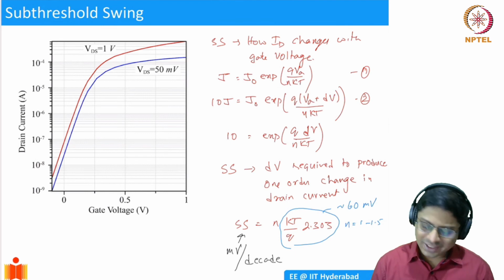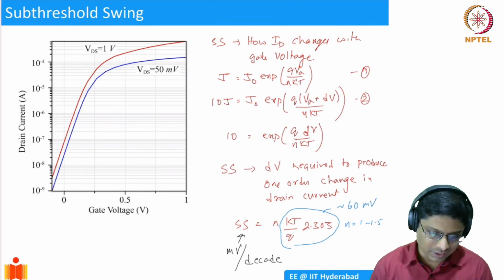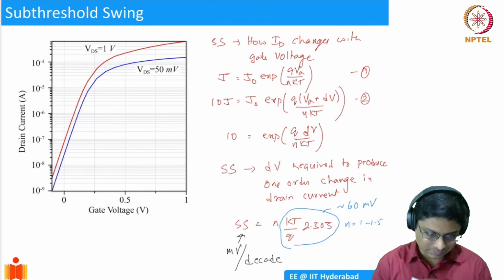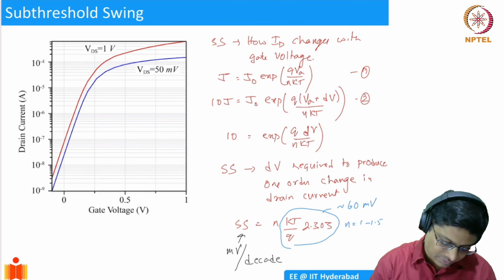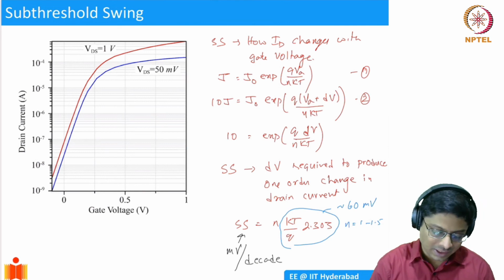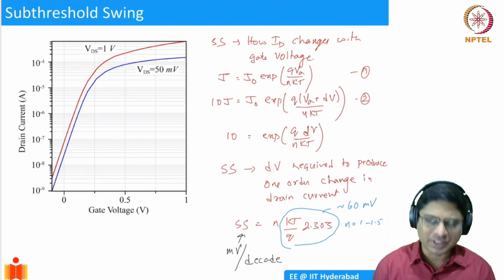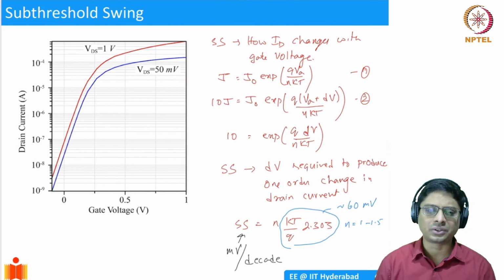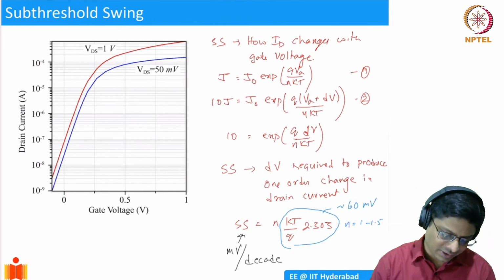So let's try to take an example and compute this. This has implications when we talk about MOSFET scaling. That's why I want to emphasize this. Let's say I take my blue curve here. There are two curves. One of the gate transfer characteristics is measured at VDS of 50 millivolts. Another one we are measuring at 1 volt. This is experimental data, you could say. I mean, this is very close to experimental data. This is actually extracted from a model, but matched to the experiment.